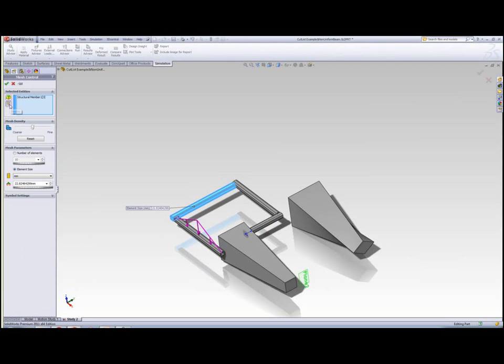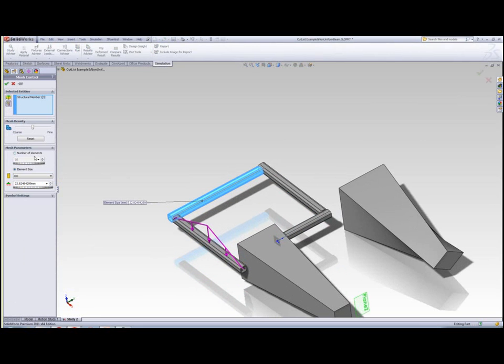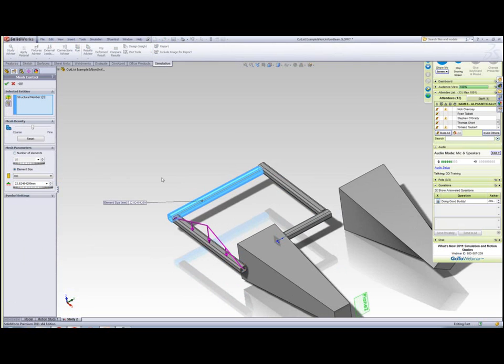If I choose a beam structure and I choose a structure, as you see there, I now have the ability to apply a mesh control, and I can select the number of elements that lie lengthwise for that particular beam. So that's something that was added in 2011, and it gives us a little more control for our models.